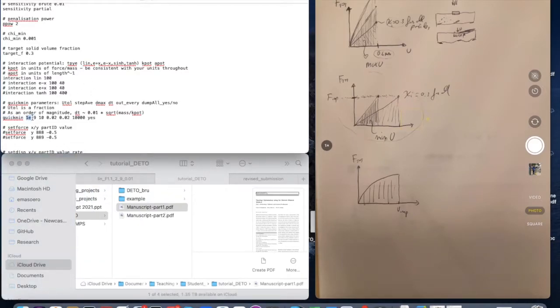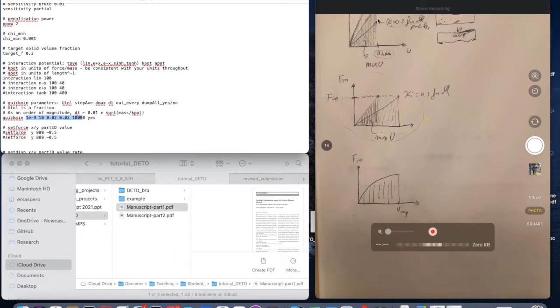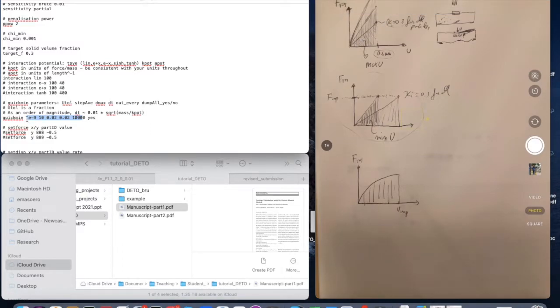And the rest of the parameters that are needed to run this simulation are performed at each step of the optimization. So the optimization is the redistribution of Xi to maximize the strain energy. The minimization is the method that allows you to equilibrate the system under the imposed displacement for any given distribution of Xi. So 10 to the minus 9 is the parameter whose description is given here.